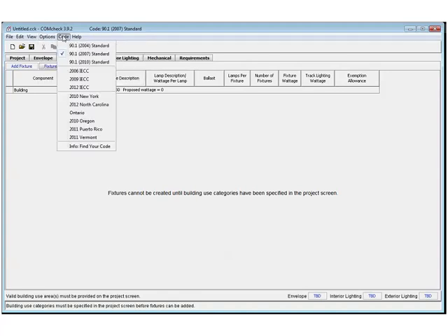So let's go back over and now look at, we've gone through those option features. Here's the Code menu. The Code menu changes with the most recent codes we work on to put into the tools. So right now I just have it on 90.1 2007, but there are other codes, the International Energy Conservation Codes, and some state-specific codes. But you also have on the very last one, what if you don't know your code? This is where, if you're connected to the internet, it will take you back out to that screenshot I showed you, the status of state code pages, and you can click on the applicable state and it'll tell you what is enforced within that state.